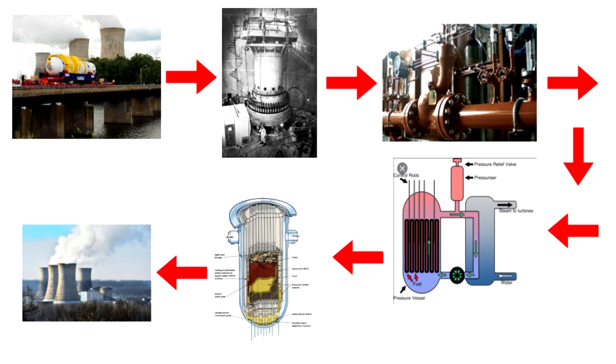This halted the fission reaction, but the latent heat of the radioactive material continued to heat up the water. Even though this heat was a fraction of what is normally produced during the fission reaction, it was enough to potentially overheat the core. 13 seconds into the accident, the PORV should have closed since the pressure in the reactor had dropped. The light indicating that the PORV was energized shut off, leading the operators to assume that the PORV had now closed. In reality, the PORV was stuck open and the steam and water was escaping from the reactor. This is known as a loss of coolant accident.